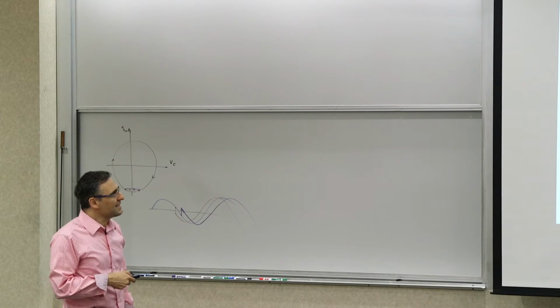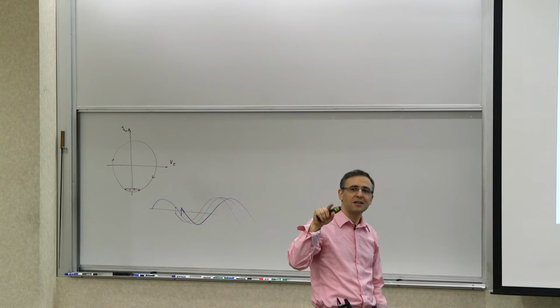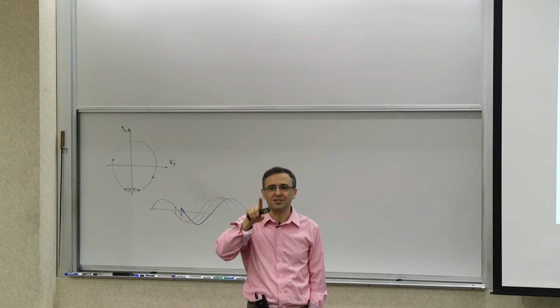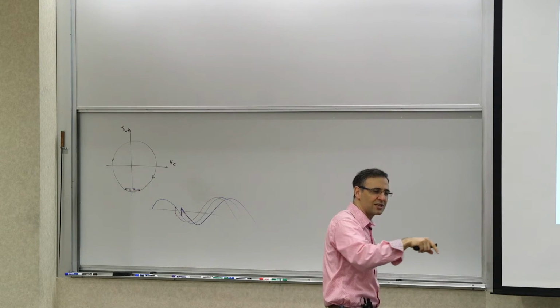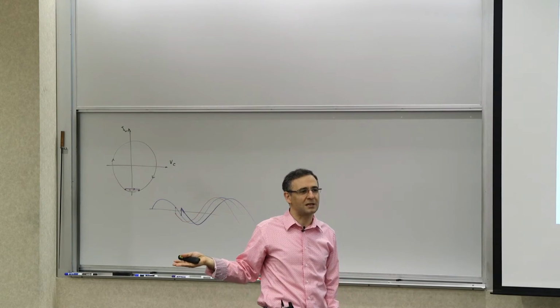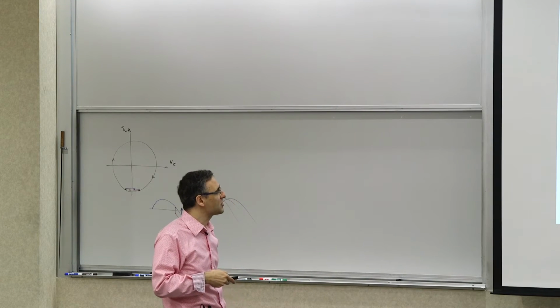The reason for this lack of dependence on the number of stages is that ring oscillators made of CMOS inverters only consume power during transitions. So it's only the number of transitions that happen. The stages that are sitting there not in transition are not consuming any power. That's why you have this lack of dependence on the number of stages.